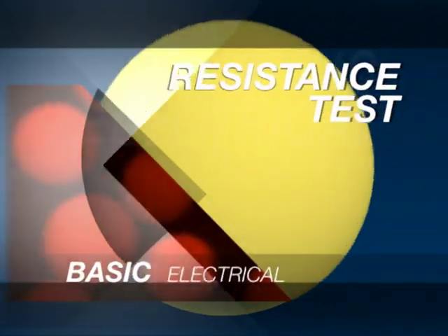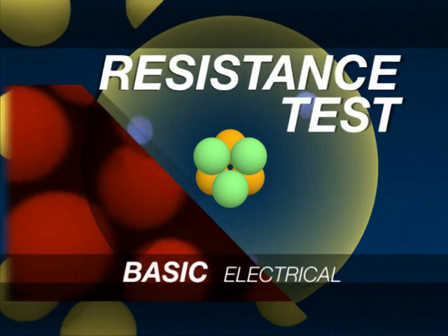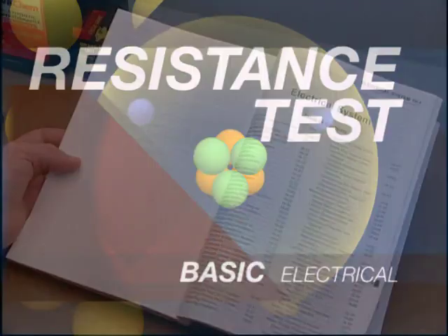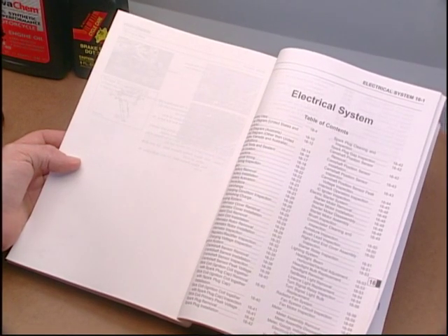Another useful test to perform is a resistance test. A resistance test measures how much a component or circuit resists the flow of electricity. Procedures for testing the resistance of each individual component can be found in the vehicle's service manual.